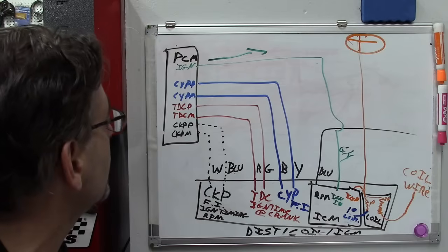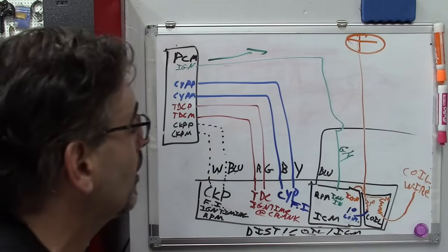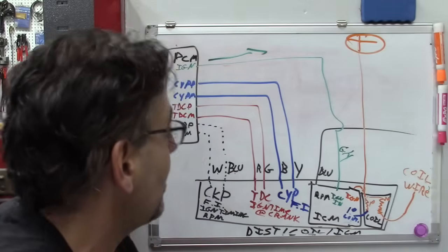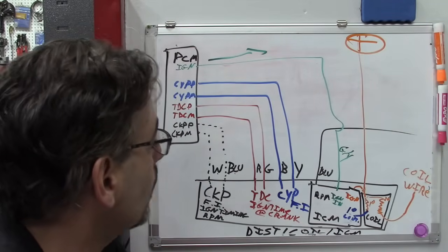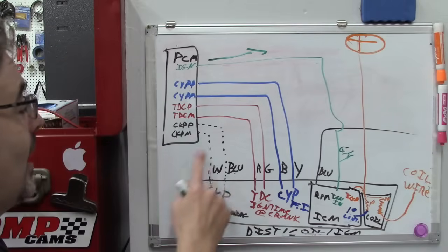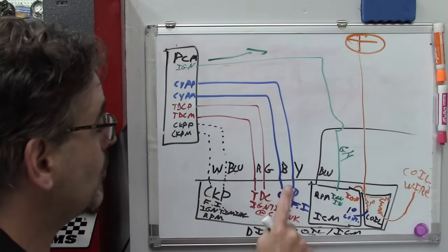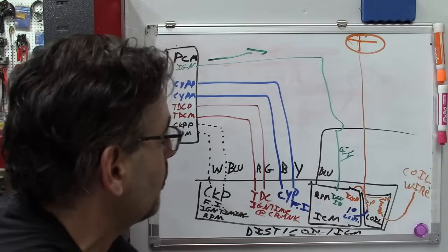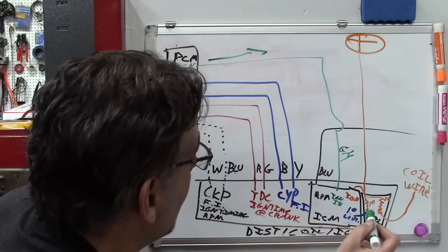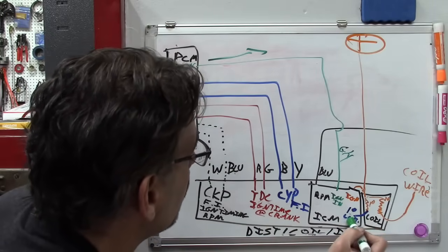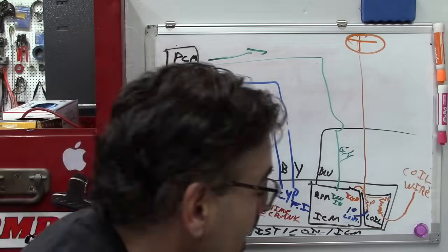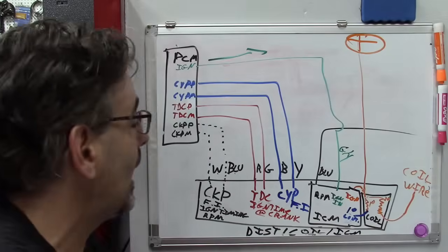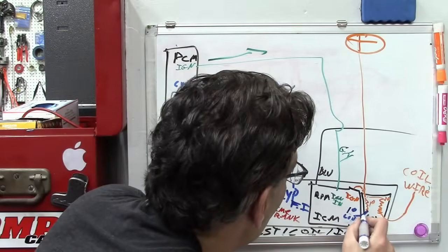So what I'd like to do is do a test on this wire. First of all, see if there is any ignition input. If there is an ignition input on this green and yellow wire, well, I am going to say that all of this works, and we have a coil problem. The other thing with the coil, of course, we've got a positive input to the coil, and it looks like we've got a primary coil control in the ICM, and that is going to be, where's my wiring diagram? Where's my primary? That's a blue wire. So I did label that blue.